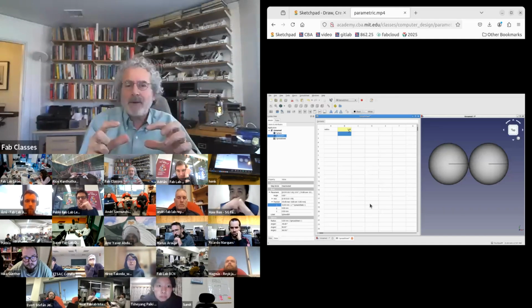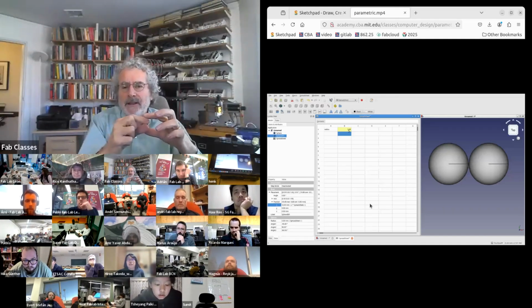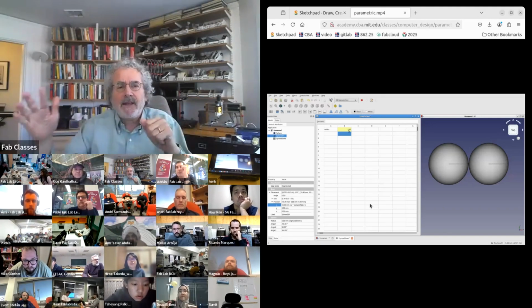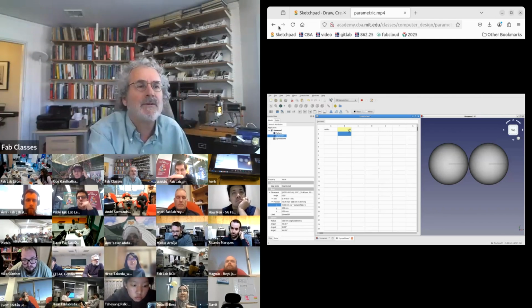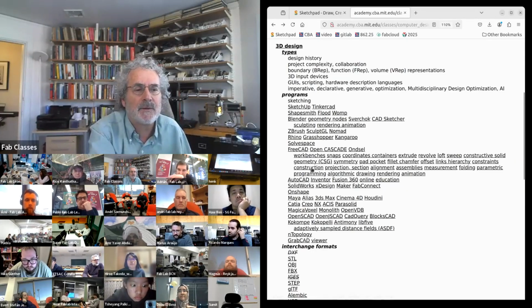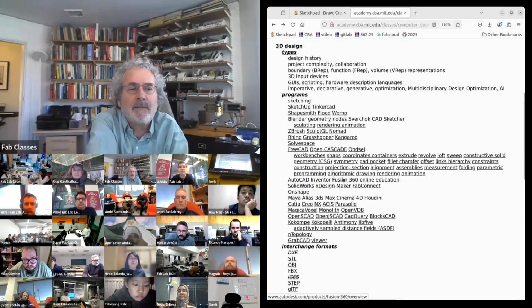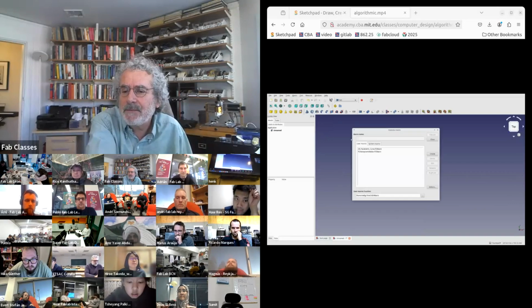So when you make your cardboard cutout, you have a formula for the thickness of the cardboard, and then you use that to make your slots, and the spreadsheet variable gets used throughout your design. And I'm going to show you interesting examples of that as we progress. So that's parametric design. And next week in computer cutting, I'll show you more examples of that. Then after parametric design,